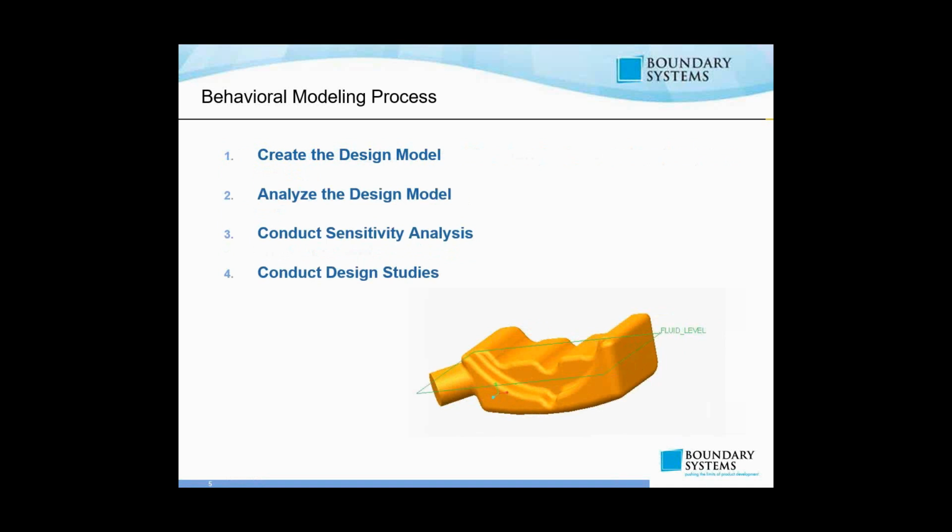So in the case of this fuel tank, for example, you're going to do an analysis that tells Creo, within that fuel tank, from the fluid level down below, it should calculate the volume of that space, right? And that is going to be the analysis you're going to do. And so in steps 3 and 4, you can then tell Creo to analyze that volume and make sure that it's equal to or greater than a certain number. In this case, 17 gallons, for example. Right, and so really, step 2 is just a way of telling Creo your goal or your objective, or what your criteria is that determines success in terms of what it is you want to get out of the system, right?